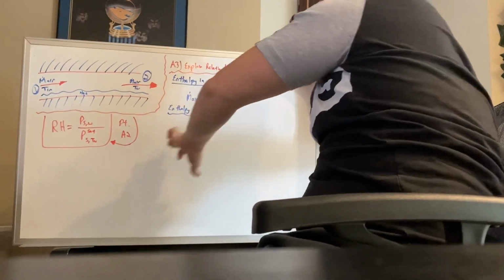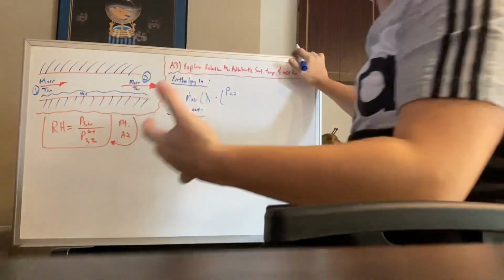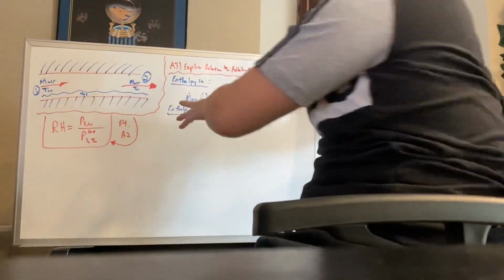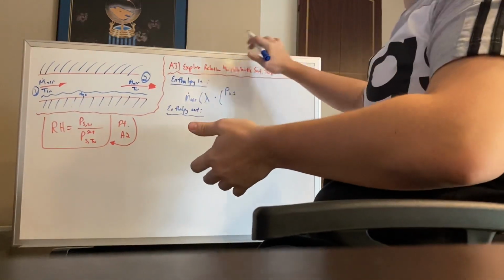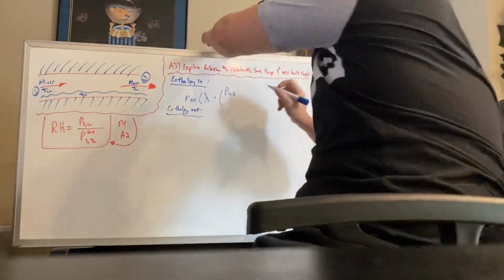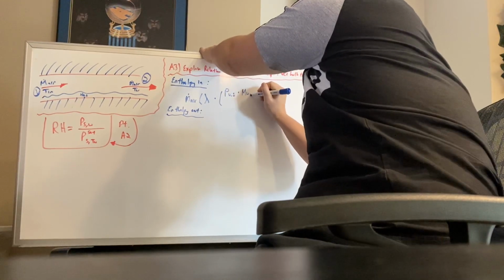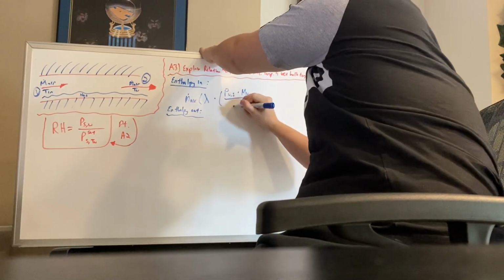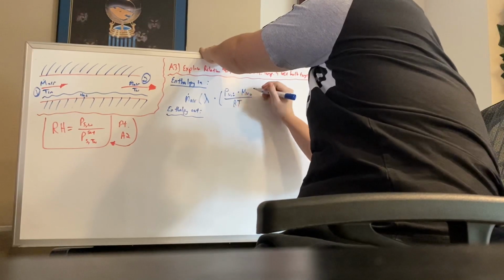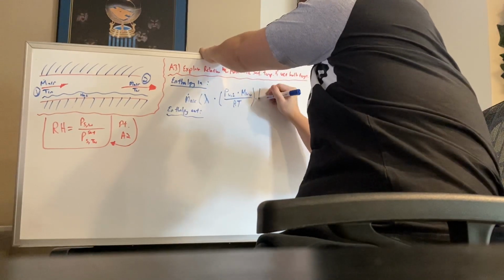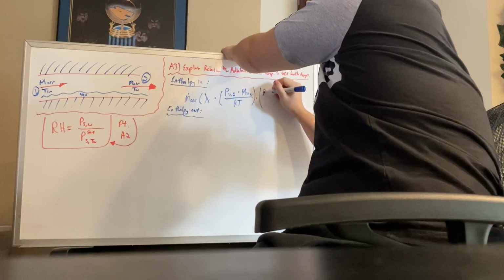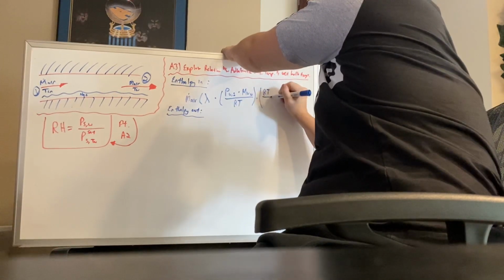Because this is the enthalpy in, we'll be looking at this left side, only the inlet feed, and we'll change that when we're looking at the enthalpy out for the second location. We want this part to be multiplied by the molecular weight of water, all divided by the gas constant multiplied by the temperature. Then we want this to be multiplied by the gas constant and the temperature again.